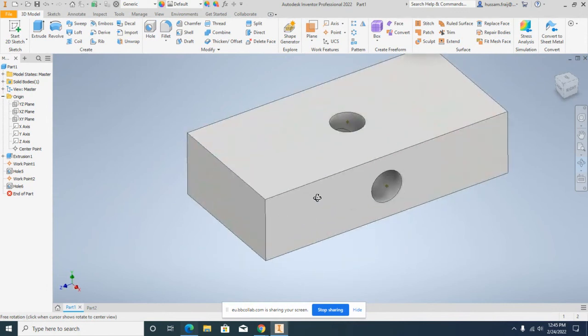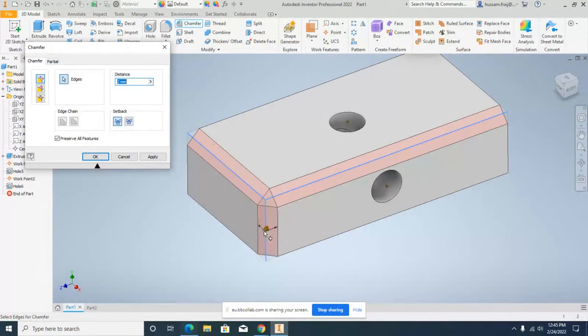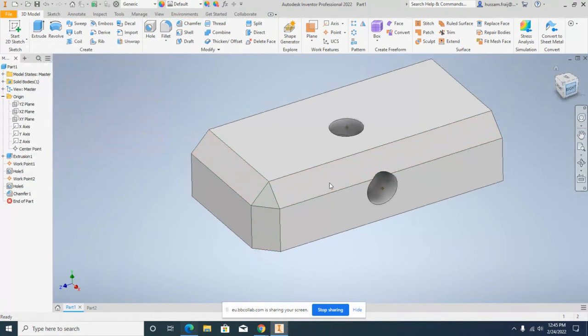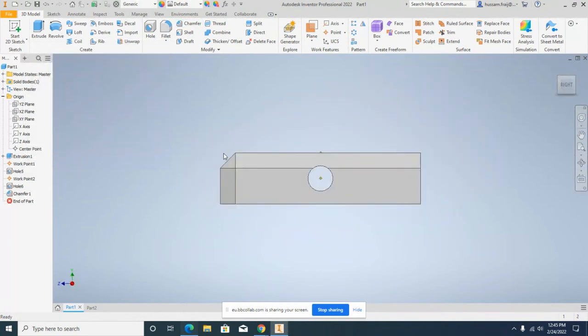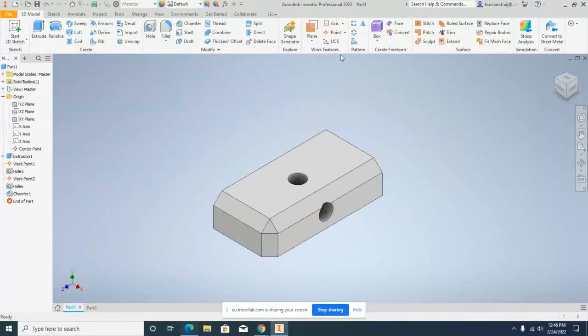So this is very important. Let's say this point here at the edge, I want to keep this corner, okay? But the problem is they ask me in the software or in the exercise to make a chamfer here, chamfer here, chamfer here, and the chamfer is 3. So where is the point that was here at the corner? It disappears, because the chamfer removes material. See, it's available here, but it's not available here. So if you still need this edge, you need it to be calculated.